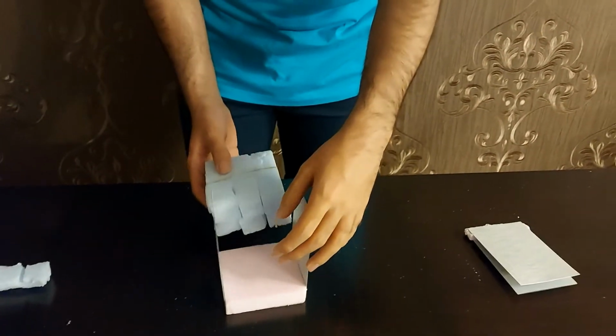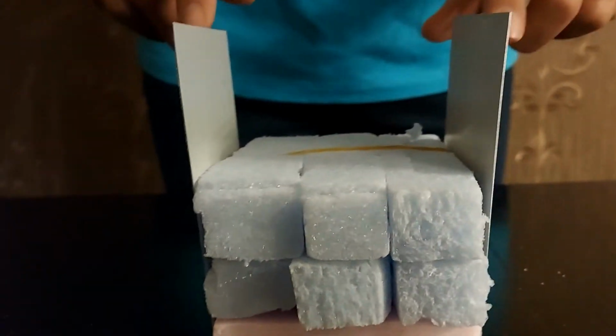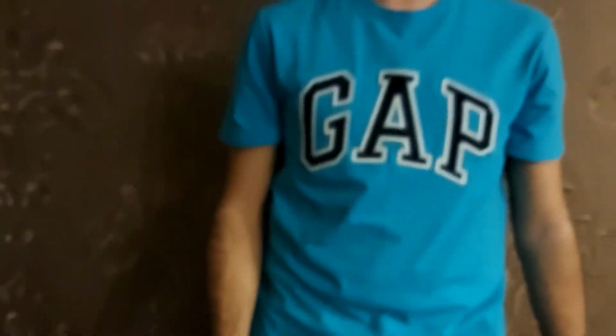Now I will show you one of my observations for the horizontal alignment of dielectric material. And for this one, I have chosen 1:1 proportion of air and PVC foam for illustration. So I would place the PVC foam in half, and the other half is naturally air, as it naturally exists in the environment. And then by connecting the probes of the capacitance meter to both of my aluminum plates, I have measured the capacitance value using the capacitance meter. Then I would have obtained the equivalent dielectric constant for the horizontal alignment of this dielectric material.